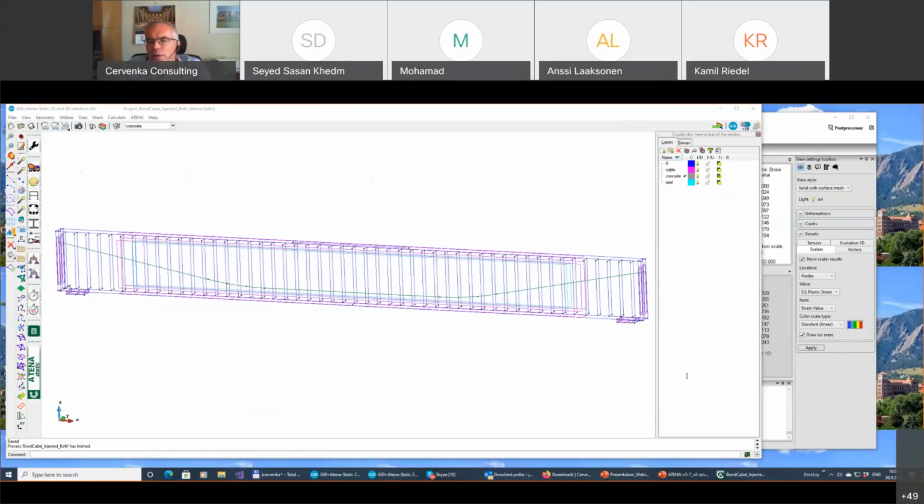because we thought that there's no need to make a full 3D or 2D transport analysis if this chloride propagation, in most cases, is a one-dimensional process. Usually it's just a distance of reinforcement from the concrete surface. Why make a full 3D or 2D transport analysis? So we are using only one-dimensional transport analysis, and this can be done within the static analysis. Okay.